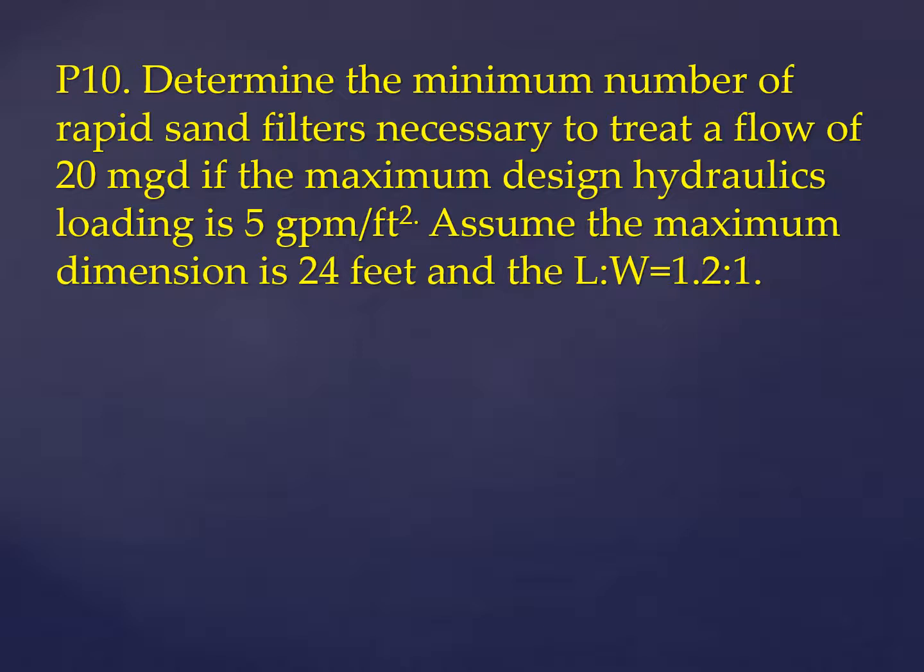Now a practice problem. Determine the minimum number of rapid sand filters necessary to treat a flow rate of 20 million gallons per day if the maximum design hydraulic loading is 5 GPM per feet squared, gallons per minute per feet squared. Assume that the maximum dimension is 34 feet and the length over width ratio is 1.2 to 1.